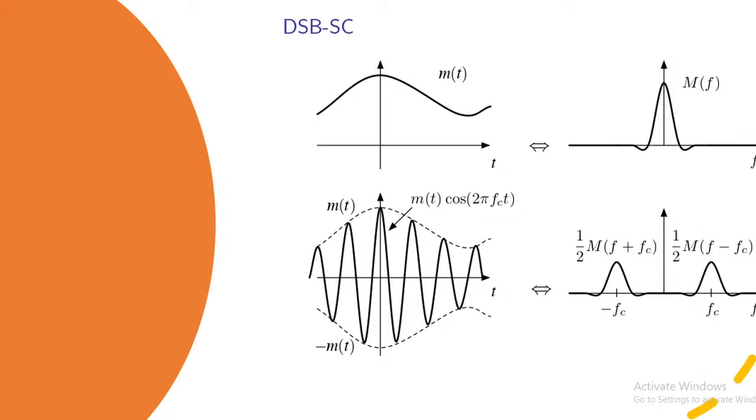So we have the modulated signal. You can see the modulated signal at the bottom left. Now, if you look at this modulated signal closely, the black sinusoidal curve has a higher frequency compared to m(t). So carrier frequency is higher than m(t). Then the amplitude of this black curve varies with time, and it is varying according to m(t).